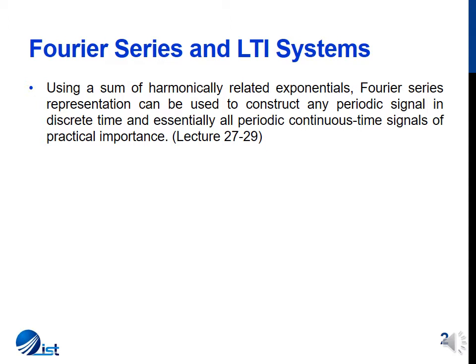Before applying the concept of Fourier series to analyze LTI systems, here's a quick recap of what we know about LTI systems and Fourier series so far. From lecture 27 to 29, we have seen that Fourier series can be used to express continuous time and discrete time periodic signals through a sum of harmonically related exponentials. By harmonically related exponentials, it implies that all the exponentials used to represent the periodic signal are related to each other through the fundamental frequency of the periodic wave.